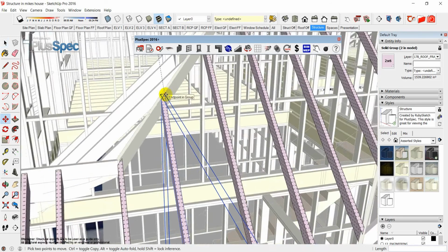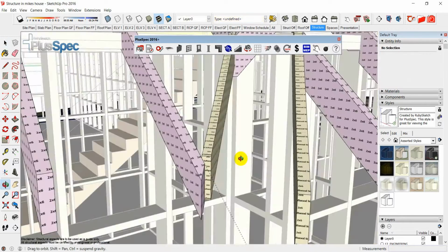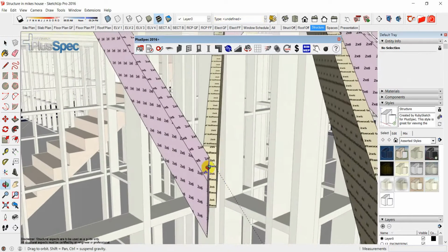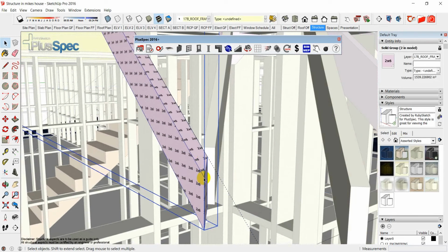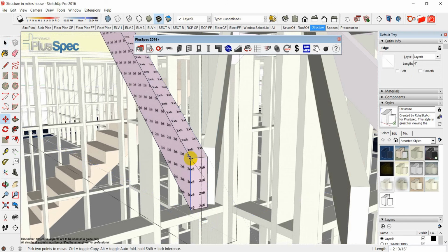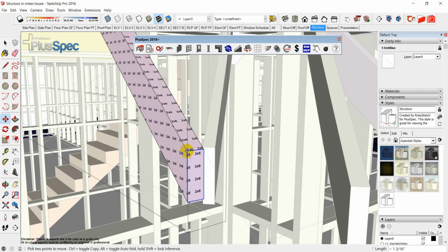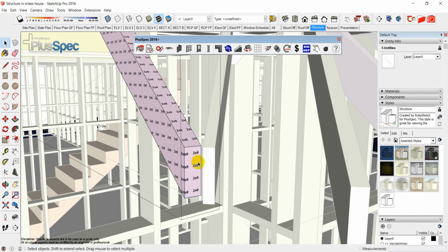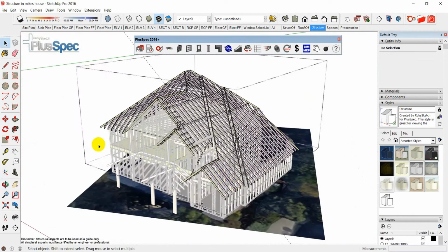I overdo things a little bit. Sometimes I'd rather have it a little bit longer so I'm not short on site, so you can see that that is there. But I understand some people are a little bit particular about that. We can go inside of here, and we don't use the scale tool. The scale tool will still give us the same size timber. We would just basically use the move tool in this instance, and I might say, well, I want to move this back up the rafter. It's estimated as well as I've done it.